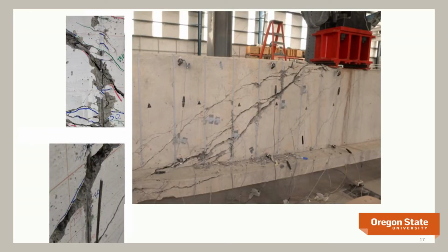At the same time, we're freezing and thawing this girder, and we're using about 120 cycles, and we've essentially calibrated that to our environmental conditions, the number of cycles we'd expect in Oregon, which would vary anywhere, depending on where in Oregon you are, from 25 years to 100 years of service life. It's like any place in the country, you have variability in terms of the number of freeze-thaw cycles that you might experience.